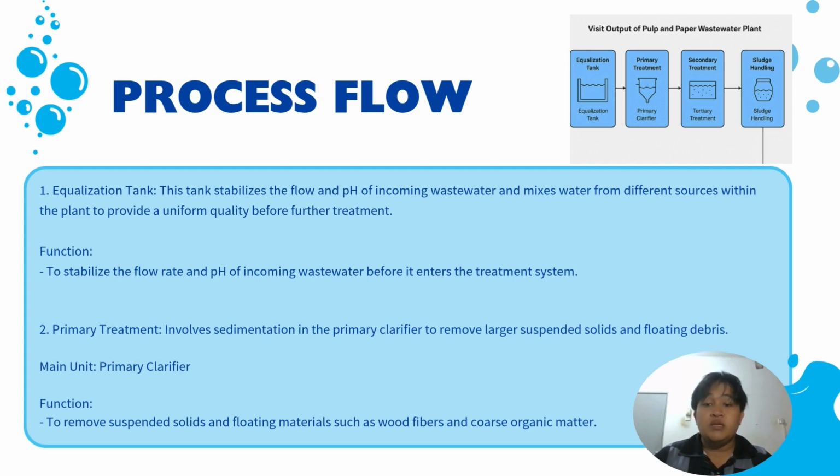Next, the primary treatment. Primary treatment involves sedimentation in the primary clarifier to remove larger suspended solids and floating debris. The main unit is the primary clarifier, and the function is to remove suspended solids and floating material such as wood fibers and coarse organic matter.